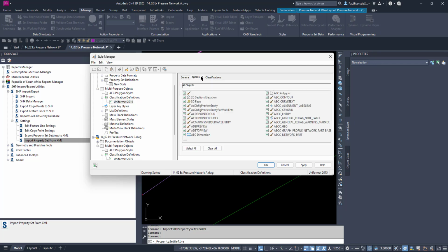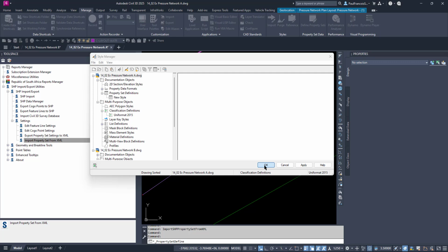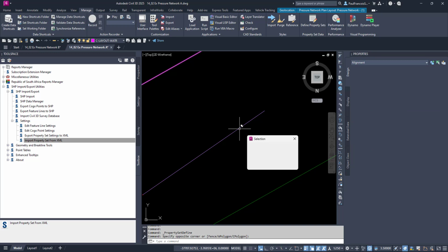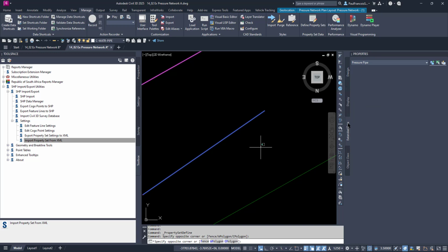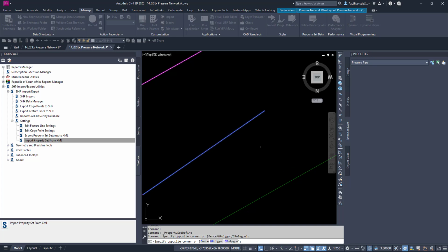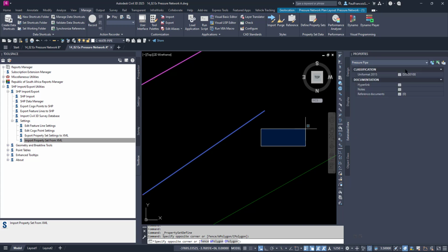It applies to everything, so it brought that through. That's great. And then if we select that pipe, and then we can go to the extended data. The Uniformat is there, and we can go and set the property as plumbing, domestic water, cold water service, and the element will then have its data, exactly what we want.